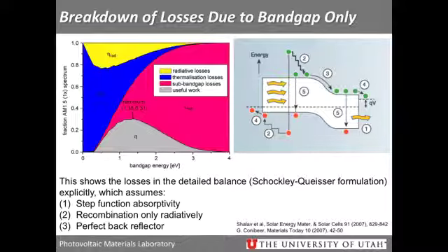The second portion here, this red portion, is kind of the opposite. As you push higher in band gap for your semiconductor material, there's a much larger portion of the spectrum that doesn't have enough energy. So you have sub-band gap radiation that is simply vibrating bonds, so heating up the solar cell, or it just passes right through it, so it's not useful energy.